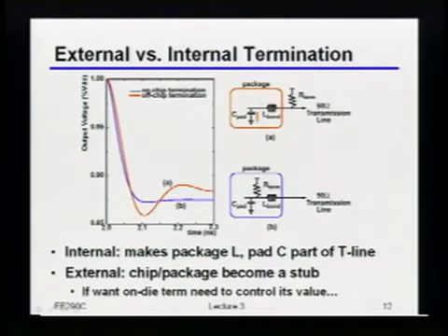Right, I have this little piece of transmission line looking kind of thing that's going into the chip and is open circuited, right? So if you look at the difference between the blue and the red waveform here, the blue is what would have happened if I really put the termination on the chip, whereas this red is just having that little stub from the package into the chip. Okay, and so you can see it caused this little ripple from the reflections happening inside of that little stub. Okay?